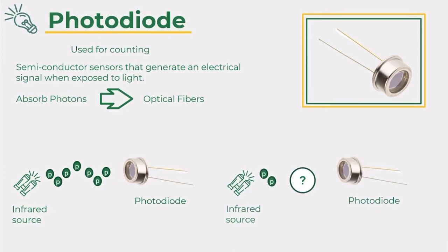The photons are sourced by an infrared laser that directly feeds to the diode. As a particle is passing, there is a disturbance in the infrared wave, and there is a brief change to the voltage produced. By counting these disturbances in the VI, the user can find the number of pills that have been sorted. The third sensor our team used was the camera.